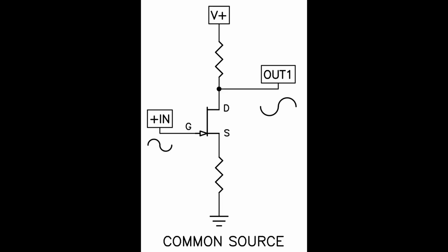We will assemble this amplifier from the ground up. We start with a JFET transistor operated in common source mode, having voltage and current gain with inverted output phase. This will form the basis of the input stage of what will be a 2-stage amplifier.